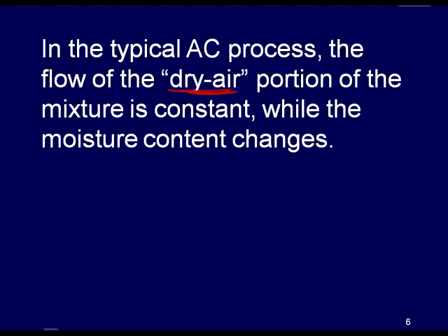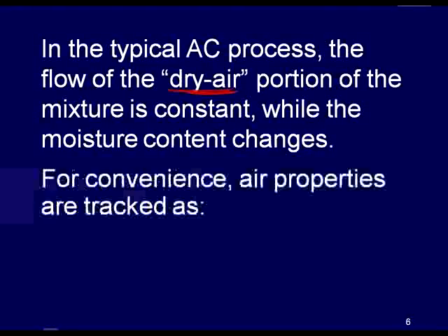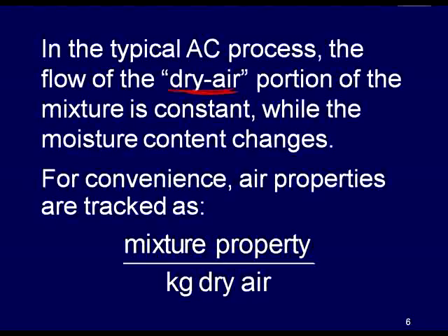So for this reason, the air properties are tracked as mixture property per kilogram of dry air. Instead of many of our properties of mixtures, where we've talked about mole fractions, now we're going to talk about mass ratios or volume ratios. We do things per kilogram of dry air because we know the kilograms of dry air coming into the process,